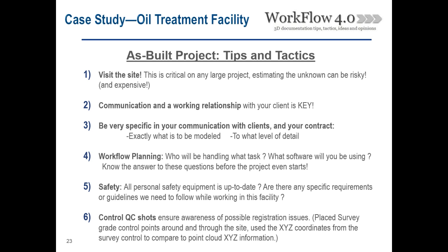Especially if you're using targetless registration, you want an additional way to be able to go through and make sure that things are registered correctly. You can do so by making cuts in the point cloud and looking down pipelines. But this is an additional way to really check the entire site, really utilizing some of those survey tools.